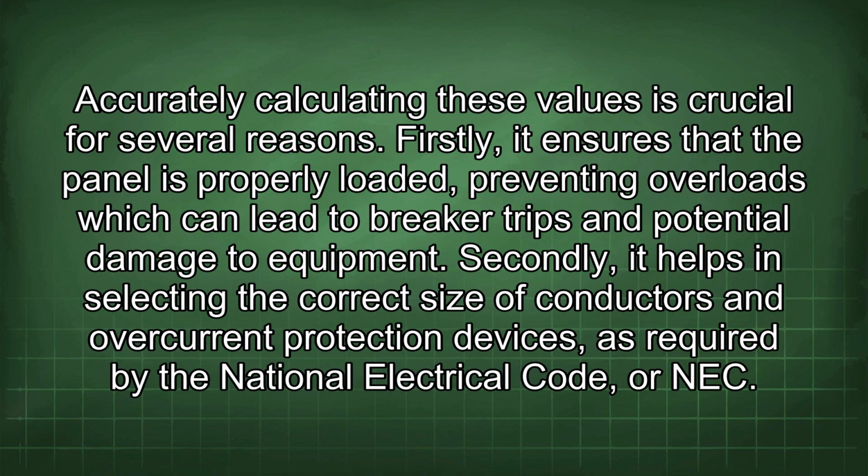Accurately calculating these values is crucial for several reasons. Firstly, it ensures that the panel is properly loaded, preventing overloads which can lead to breaker trips and potential damage to equipment. Secondly, it helps in selecting the correct size of conductors and overcurrent protection devices as required by the National Electrical Code, or NEC.